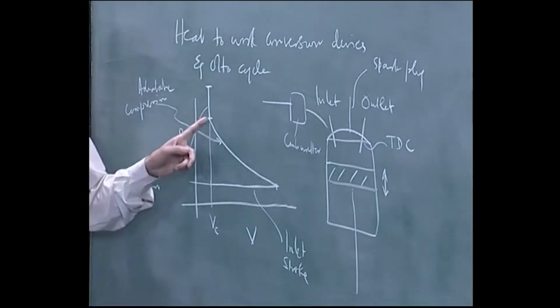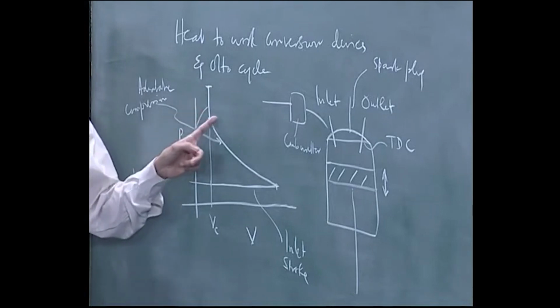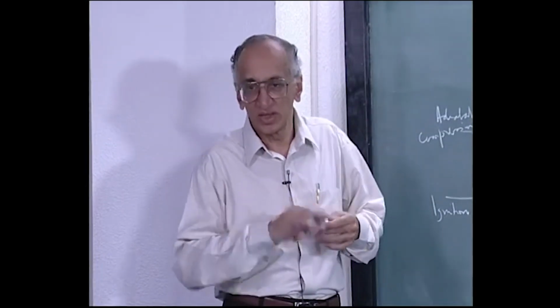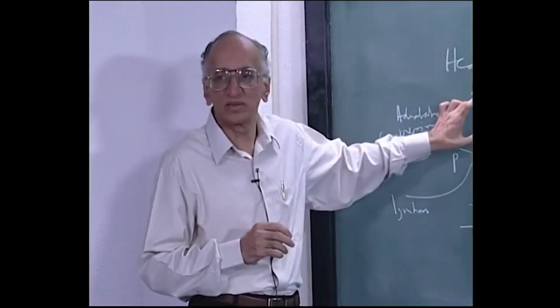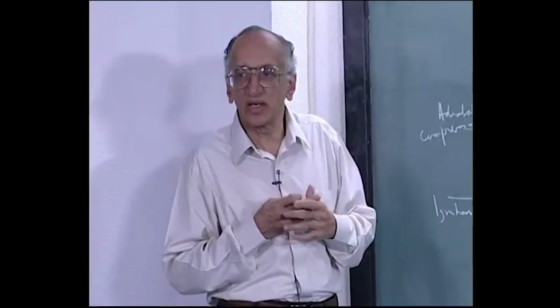In the case of a diesel engine, the pressure is much higher and the ignition is supposed to be at constant pressure, because as you inject the diesel it burns by spontaneous combustion and that takes longer than spark ignition. So actually the piston moves back and the pressure is maintained.